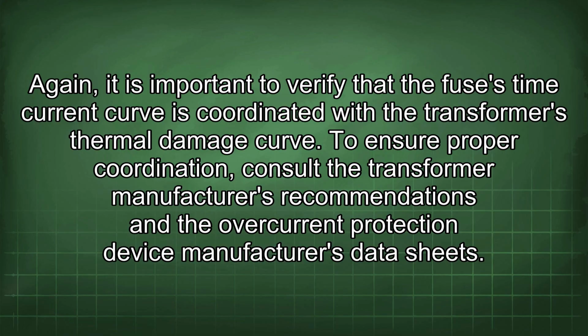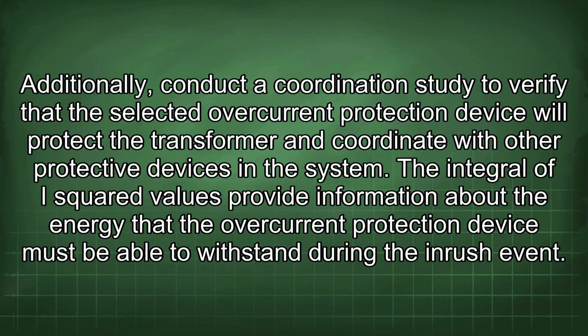To ensure proper coordination, consult the transformer manufacturer's recommendations and the overcurrent protection device manufacturer's data sheets. Additionally, conduct a coordination study to verify that the selected overcurrent protection device will protect the transformer and coordinate with other protective devices in the system.